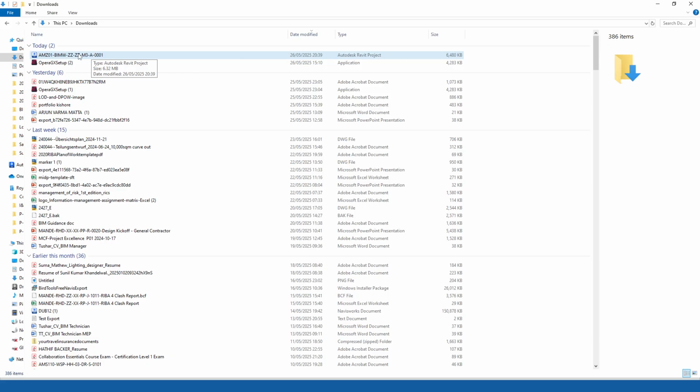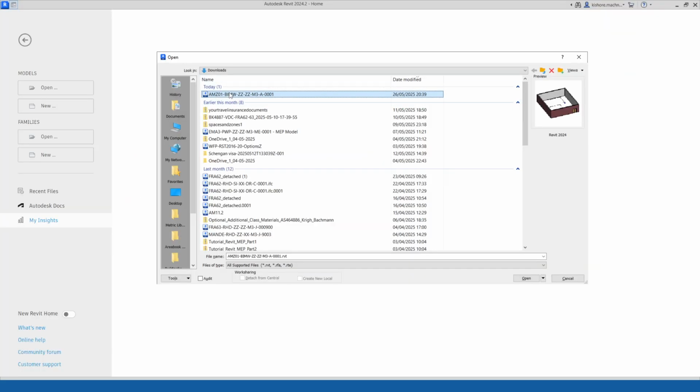So you have only Revit 25 and you get a 24 model. What will you do now? You can't open the model, right? That is why you should not open the Revit model by double clicking it here. When you click on open Revit model here, you can see the Revit version. If I have Revit 25, I can open the 24 by upgrading the model. So never ever double click on the Revit model.